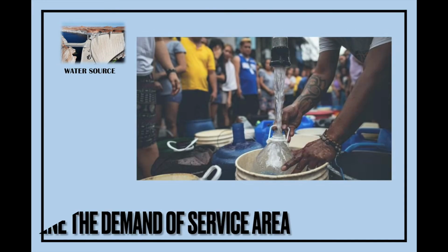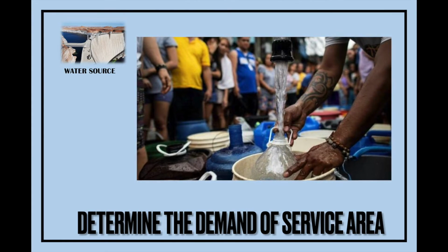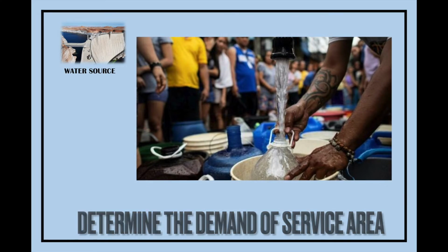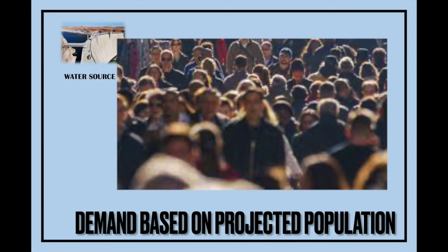Fourth, determine the demand or the service area. Make a projection on the demand or check the water source capacity as against the demand if it is sufficient, or you need to look for other source to satisfy the demand.